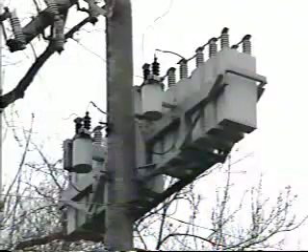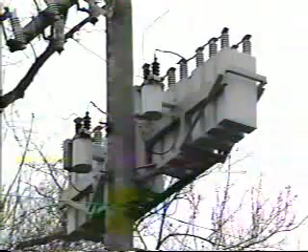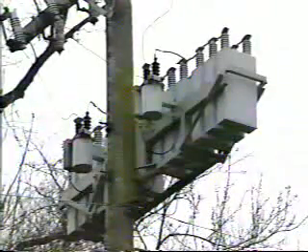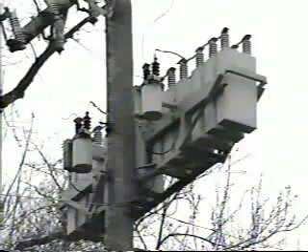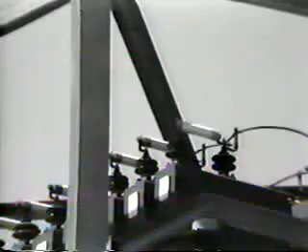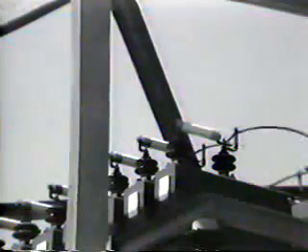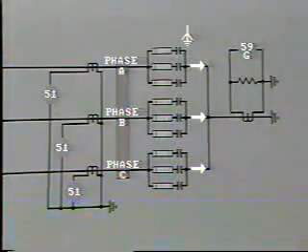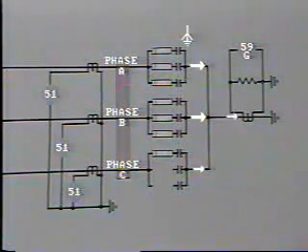The capacitors are susceptible to serious damage if a heavy fault current flows. The casing may rupture with consequent spillage of insulating fluid. Each individual capacitor is protected by its own fuse. If several capacitors are isolated due to blown fuses, there will be some unbalanced current flowing through the neutral.